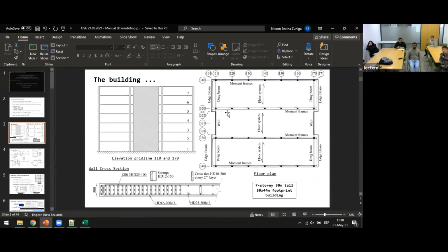You mean that one and the frame? So you have in this picture the floors spanning in the vertical direction on the slide, and then you have the frames perpendicular to it. For example, within the plastic hinge zone above the column, how are they contributing to the stiffness? What I wanted to capture was the transverse direction, not the longitudinal. So I never expected plastic hinges to form in the frames. The frames were just there because they were part of the structural system.